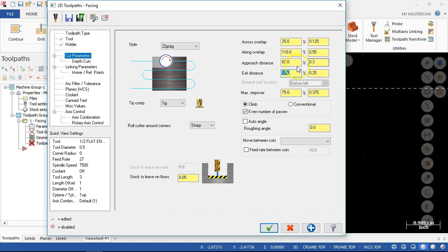All right, so just maybe a little bit extra on the approach, especially if we cut the material long. Our saw is not the greatest; it's cutting a little angle, so I add 60 thousandths or 80 thousandths of material. Then when I do that adjustment at the work offset, I'm just allowing it to come down and do that face without touching the material first, potentially chipping teeth. All right, max step over 375, 75% of the tool. So that was kind of the math between the 1/8 inch and the 375. Those should add up to our diameter.